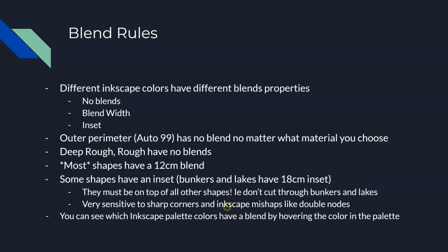They must be on top of all other shapes. You cannot cut through bunkers and lakes, because if you cut through, what does that inset and that outset blend go to? It just gets snapped off, okay? And there's really no reason you would cut through a bunker or a lake anyway, right? If you want to do a bridge or something over a lake, you add the bridge later on. You don't do a cart path through the lake, okay?